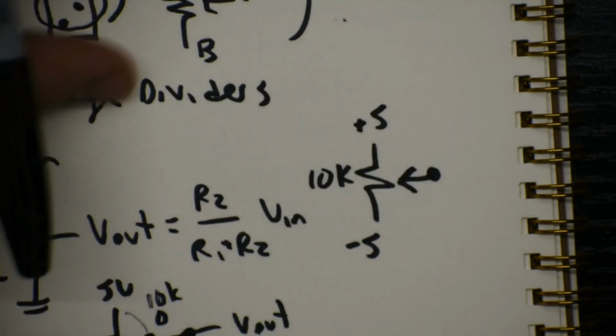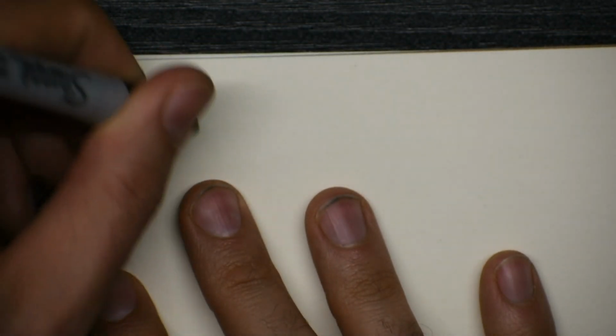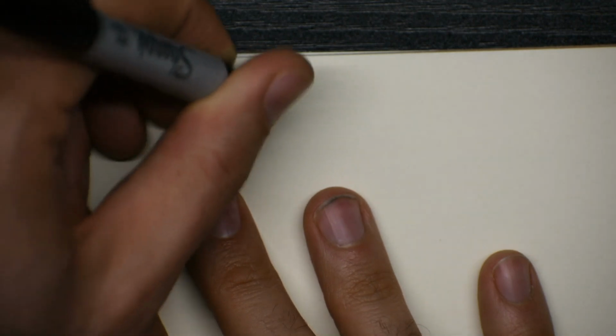Okay, we don't use comparators a whole lot unless we're kind of at the end of a circuit and we need to make a decision which voltage is bigger. Usually we use our op amps with negative feedback. So these would just be regular amplifiers.